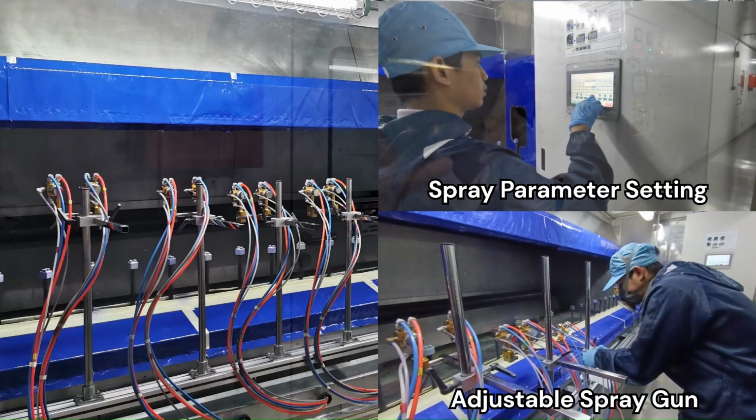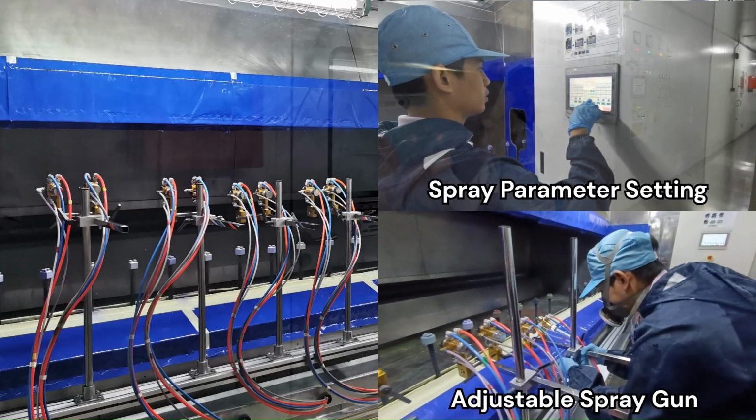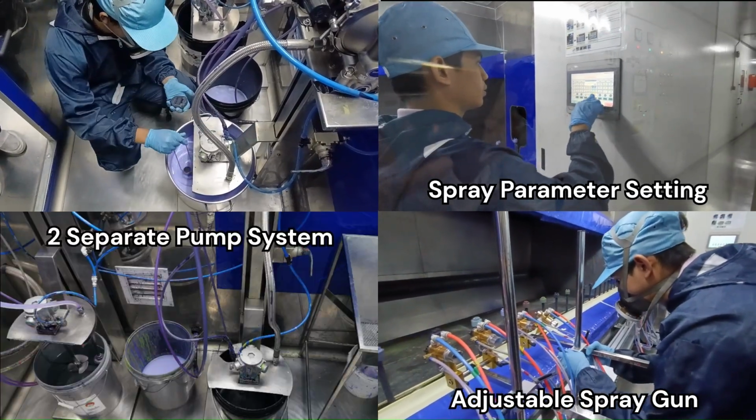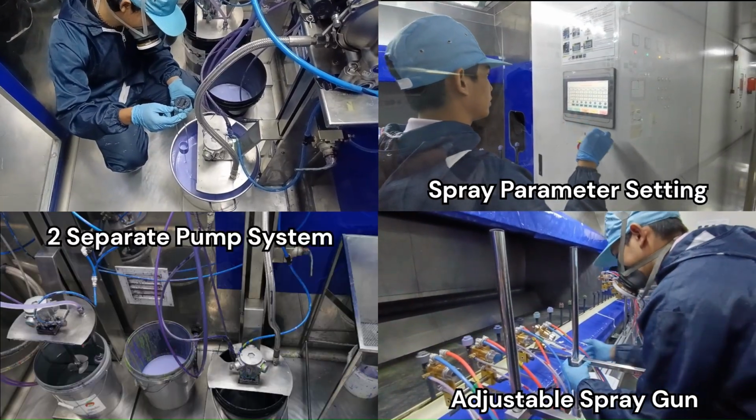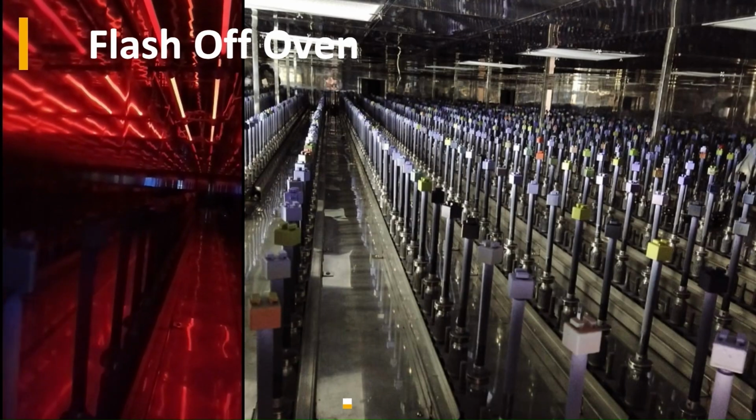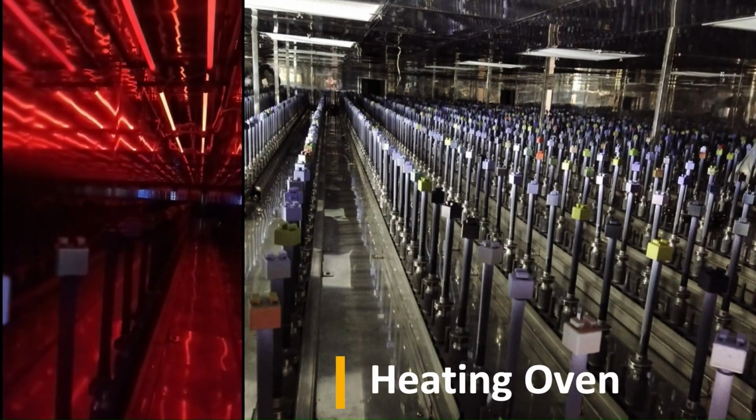8 sets of spray guns are adjustable for each booth. 2 separate pump systems for water-based and solvent-based paint are available for each spray booth. Painted products will pass through a flash-off oven to heat up slowly, and then go through a heating oven for curing.